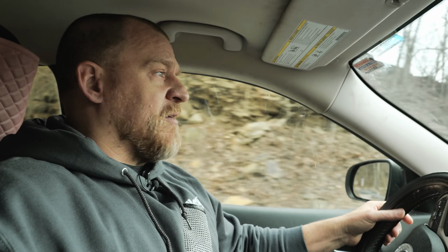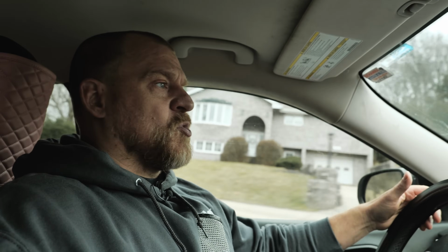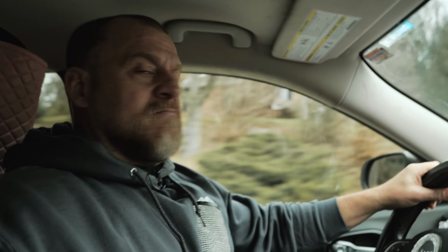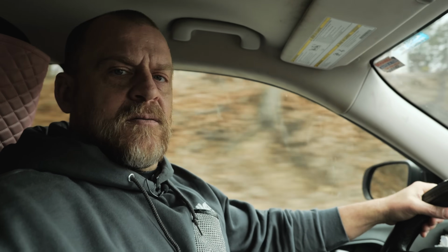They'll use a voltage equivalent, and all the cars are different. So if you're looking at an unfamiliar sensor and you're not sure which number here is rich and which number is lean, you do that test. Test drive it wide open for your rich side and decel for your lean side. Look at your numbers. So that's when you'd use this test.